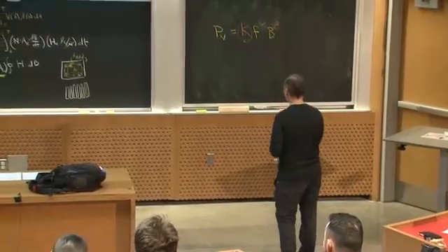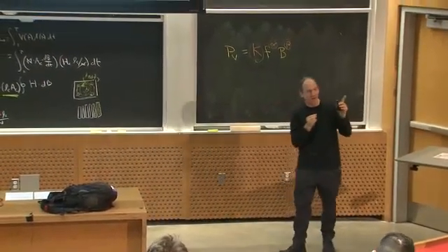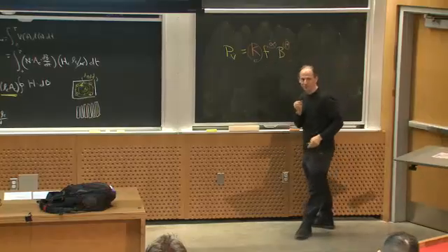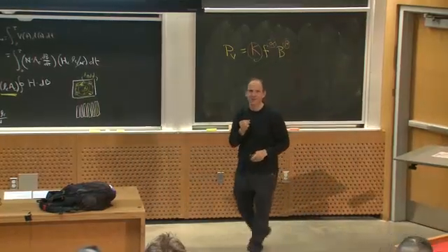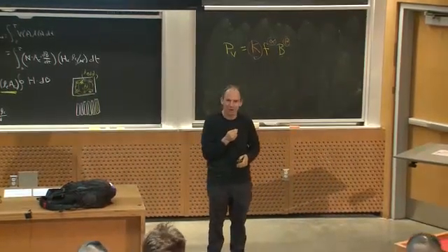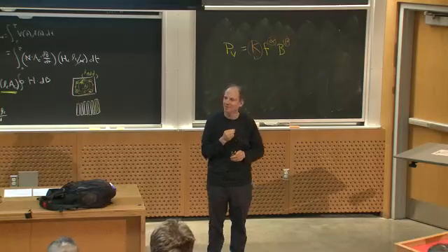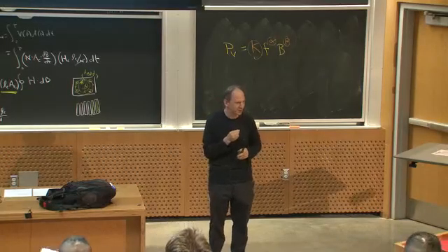So all you've got to do is be careful. If you're going to have a lot of AC flux density, figure out your loss per unit volume and use it. So that's my very hand-wavy introduction to loss in magnetics. I think it'll be enough to get you through to designing some pretty reasonable inductors and transformers.